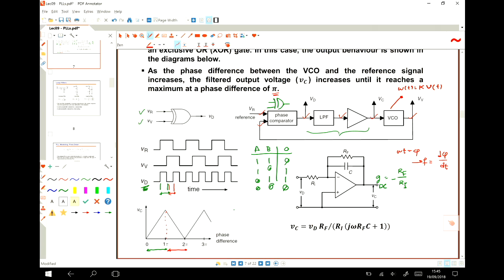When you turn on a frequency synthesizer, the output frequency that it generates and the input frequency that we apply could be totally different. But then we sweep from the starting frequency and look at the output phase to see whether it is locked or not. I have a simulation file here, and I'll show you that we increase the frequency, and when we get close to the frequency of the carrier or the reference, they get locked.